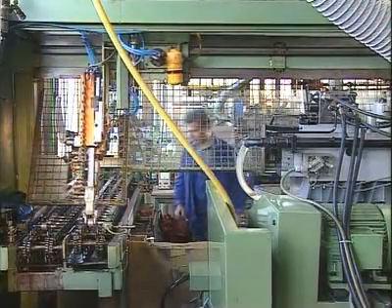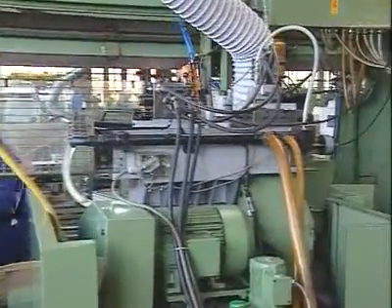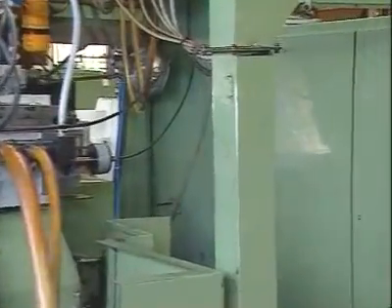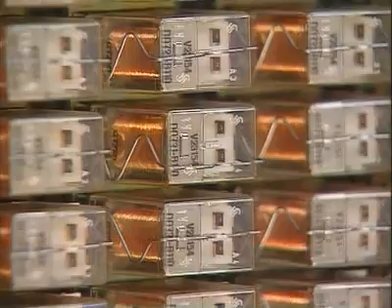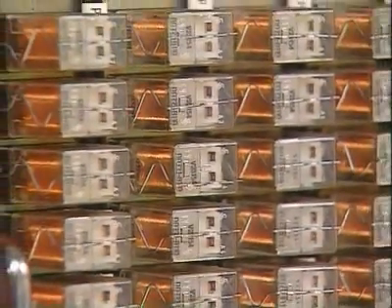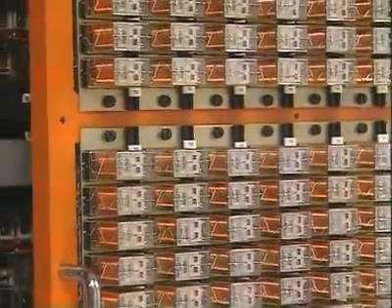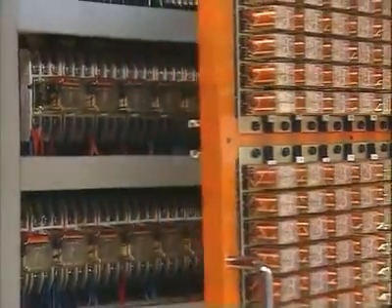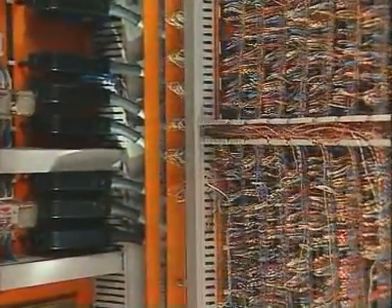Hardwired controllers are systems in which the sequence and the functions are determined by appropriate fixed wiring of the individual elements of the control part. Electrical lines are primarily conductors for electric current, but the arrangement of the various elements and the way they are connected determines the function of the system. Changing the program sequence requires a change to the wiring.